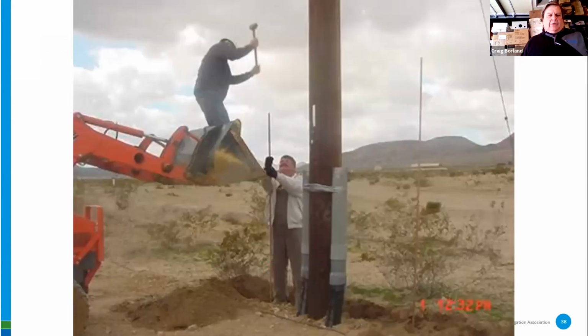And in setting up a proper ground, don't be this example. First of all, that's not an appropriate ladder. Second of all, holding the ground rod like that with a guy with a sledgehammer just looks like an opportunity for something bad to happen. And by the way, 8-foot, 10-foot ground rods need to be 8 to 10 feet away from the thing you're protecting with the ground. This here is like 3 feet away from the power pole. That's not the appropriate location for the ground rod. That ground rod is definitely too close to the pole, not appropriate.